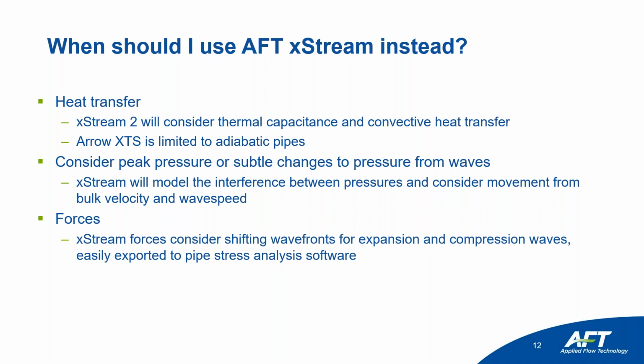So if you're doing a stress analysis, if you're building a support for a steam blowdown, for example, you might need to look at AFT xStream, run the valve opening, and see how the forces change from not only pressure, but the changes in flow rate. From that, you can export it to your pipe stress analysis tool, whether that be AutoPipe or Caesar, or I'm sure Roar2, I think, can also read those force files.